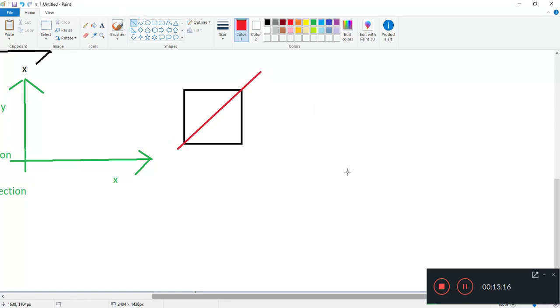We draw the y equals x line, and we know the positive stresses are the ones pointing towards that line. Okay, so now, how do we name the stress? First, we need to know if it is a normal stress or a shear stress. Shear stresses are the ones that are parallel. They slide along the plane this way, and that is tau.